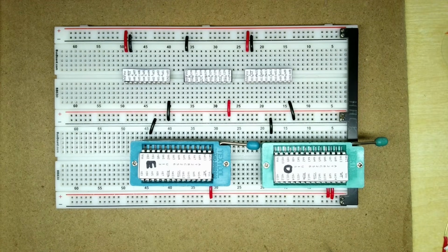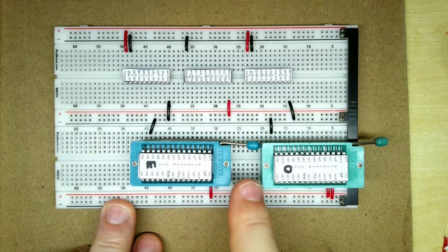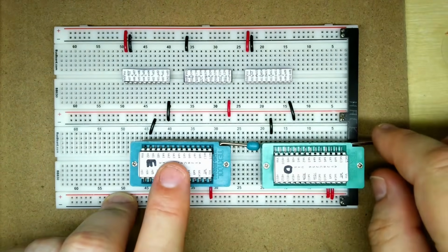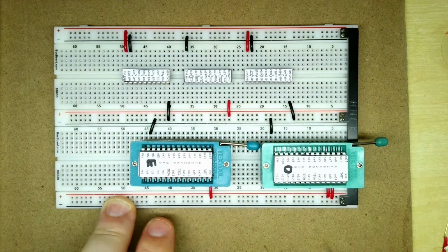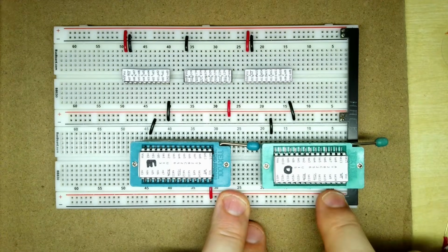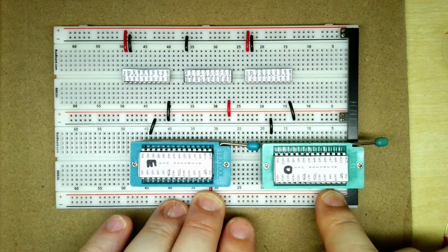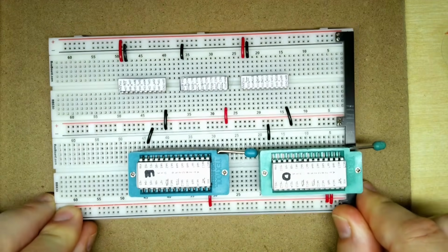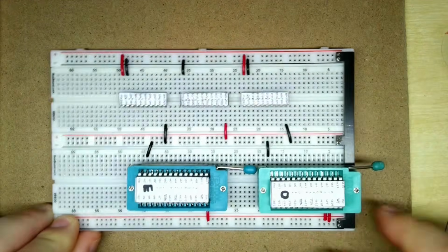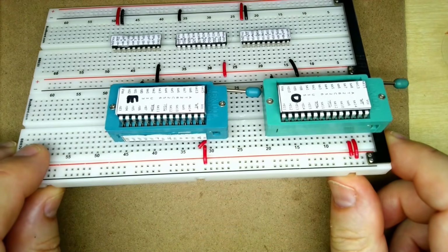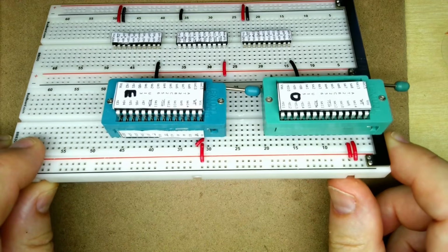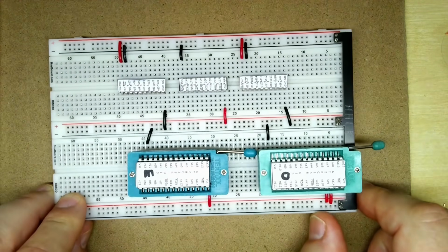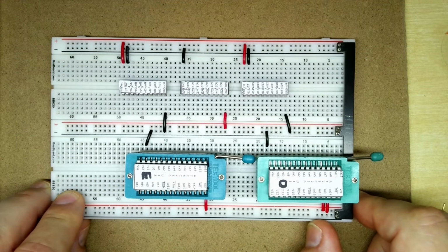Now, when putting zero insertion force sockets in, it is important to make sure they're spaced out so you can still actually do and undo them like that. I have in the past left myself too little room. And I've already laid them out with the power here, so it makes it a bit easier to see where everything is. You can see there's a couple of holes on this side, and if you look over here, there's a couple of holes on this side as well. Just the orientation of the camera means you can't easily see it. So hopefully that should give us enough space either side to wire everything up.